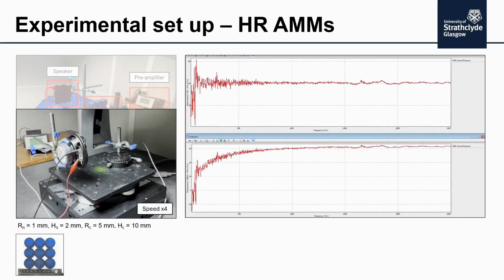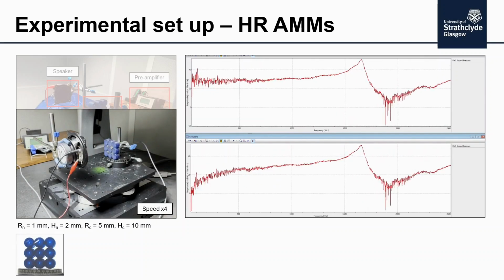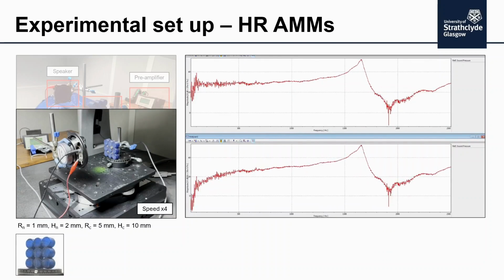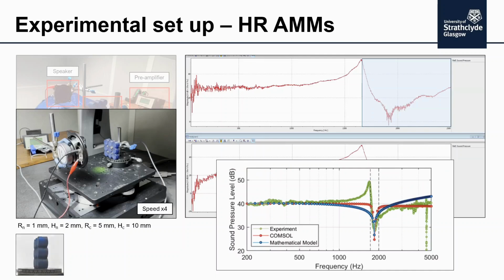If we test them with periodic chirps, we see before the metamaterials a nice and flat response, and then this metamaterial, these dimensions are calculated to present the center frequency of the bandgap at around 1850 hertz. We'll just call it 2000 hertz. It will also depend on the end correction factor that you use. And we see a very clear 20 dB decrease there. There's a very clear bandgap. And as I said before, there's nothing too interesting in this. This is very well understood for 200 years. If you run your mathematical equations or your simulations, you can get very nice predictions of the acoustic behavior of this.